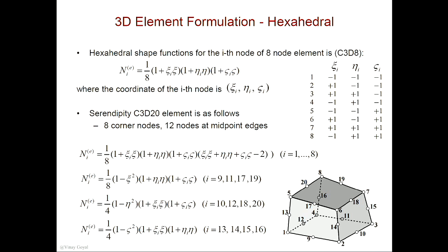How does the first shape function work? For example, for N1, how does that go to 0? Yeah, you just go to this table. What about psi? Yeah, so this table gives you the values of psi_i, eta_i, and zeta_i. So you plug in the values for node 1, minus 1, minus 1, minus 1. Plug it in there. How about the psi itself? The psi, eta, and zeta are the coordinates of the cube, right? The shape functions have to have a coordinate, right? It goes from minus 1 to 1, the cube. I didn't draw the cube here, but the Abaqus manual has a cube given there.